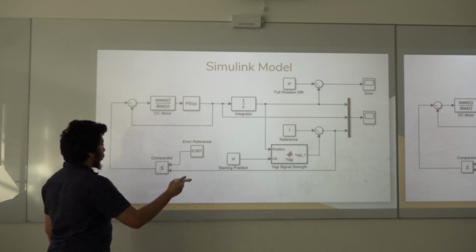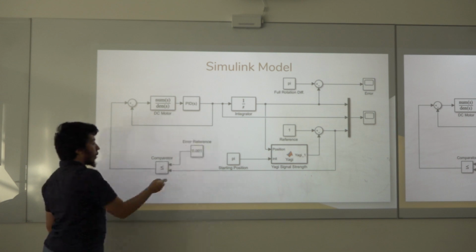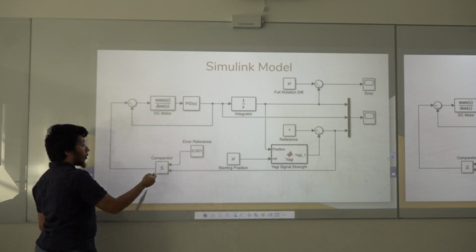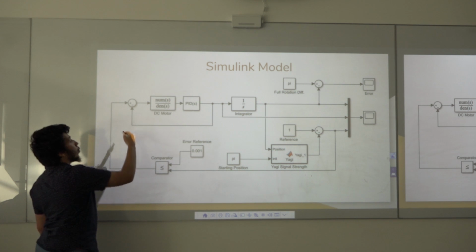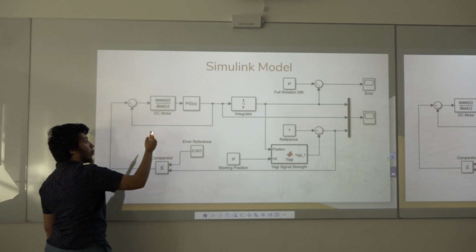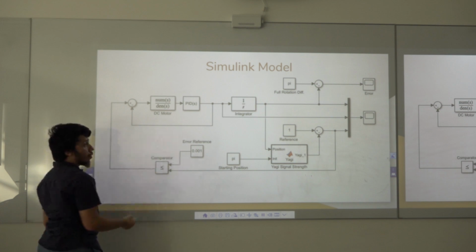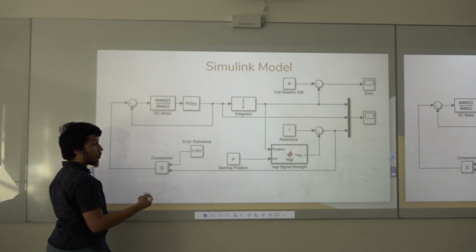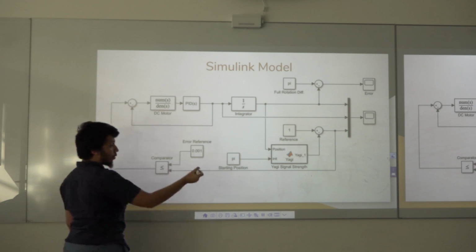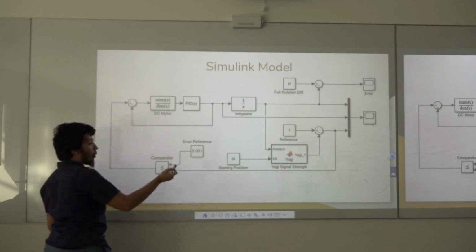When we take the difference of our signals for the function of our system, we run it through the comparator. The comparator gives an on or off signal for the motor. This signal drives the motor, which is in a feedback loop with this controller, and continues until the comparator gives an off signal. The comparator will give the off signal once the calculated signal strength of our Yagi antenna matches our source.